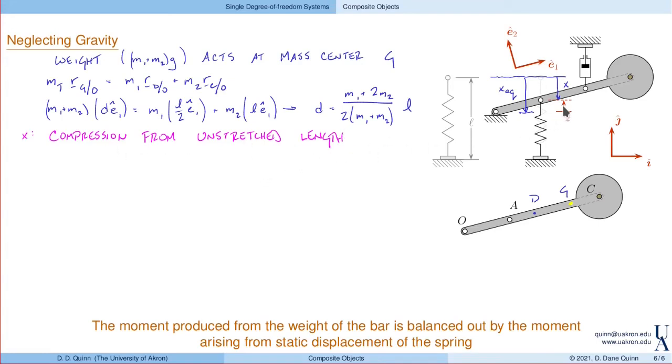As a result, we can relate X and our coordinate Z that we used earlier together with this equilibrium stretch. Right? So X here is X equilibrium minus Z. As a result, when we again go and look at the forces, once again, I've got a reaction force. I don't know anything at all about that. I have a spring force. And now I'll choose to write that in terms of X. Right, so it's K times X in the J direction.